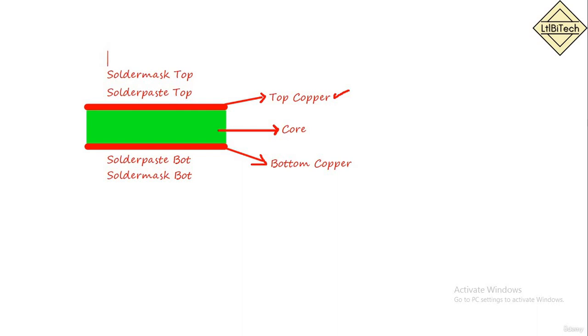On top of the solder mask top, we will have the silk screen top, not the paste mask, which is used for ink printing on the PCB. You might have seen the component body area and the component references printed on the PCB. That all comes under silk screen top. If it is top, it will be on the top layer of the PCB. If it is bottom, it will be on the bottom layer of the PCB. So these are the components.